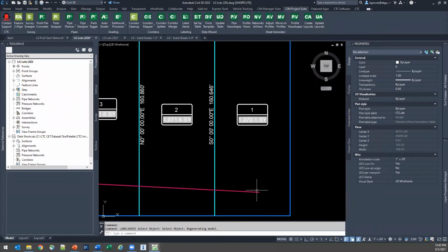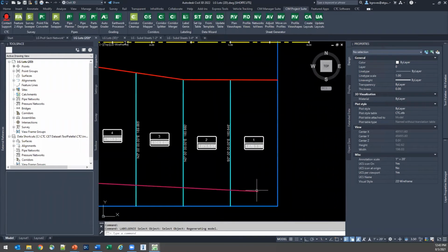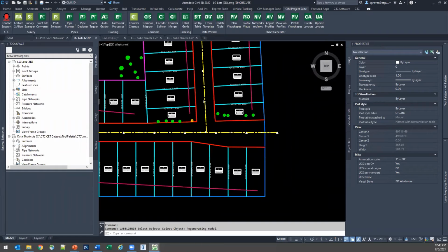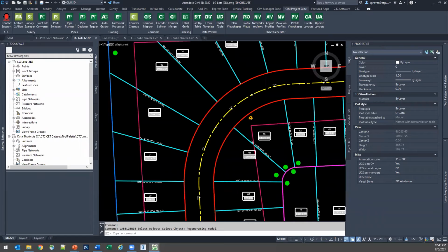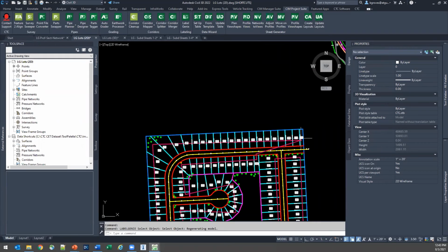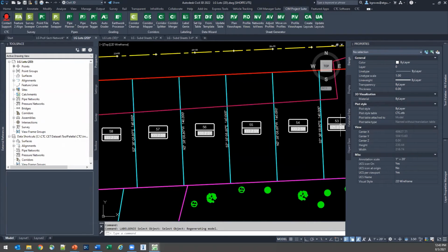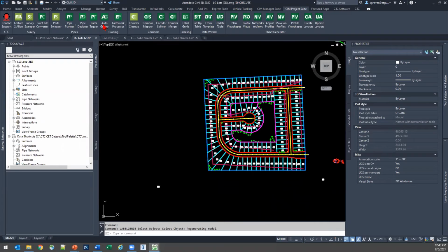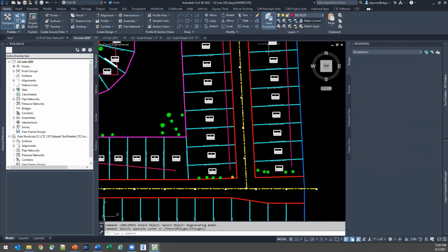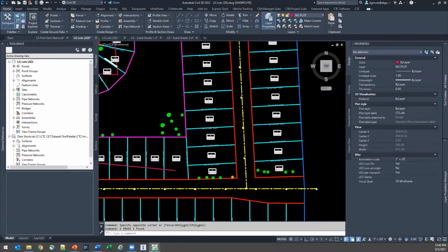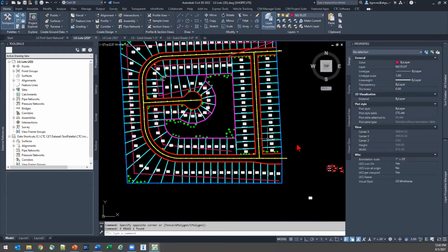Clearly, I started my polyline here in the southeast corner of my site. And as I continue to move through, here we're at 39, then we go to 52, we jump across, here's 53, all the way down the line. If I set this no plot layer current, I will delete this path polyline over there for my counter. Let's run Label Genie, see how it responds to that lack of an input.